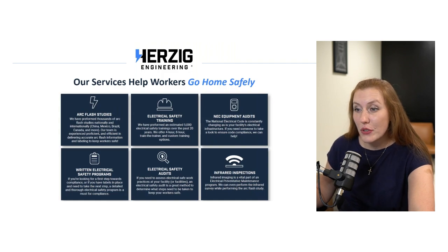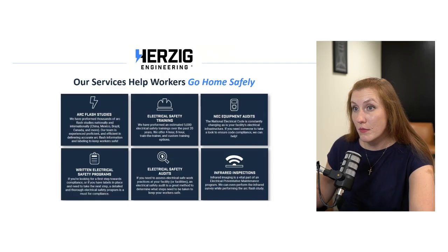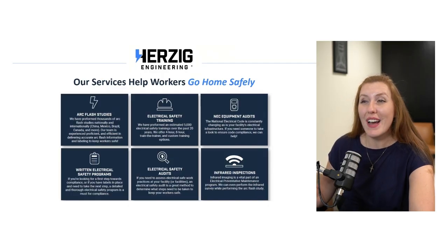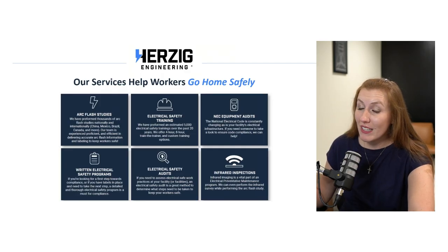All of that goes into your risk assessment to determine if arc flash and even electric shock protocols are necessary to be in the room. Sometimes, depending on the situation, why you're in there, the condition of the equipment, how you're interacting with it, even just walking past it, it's justified to be protected. I know people do not like that answer, but that is the reality. You need to be protected if it's in bad condition.